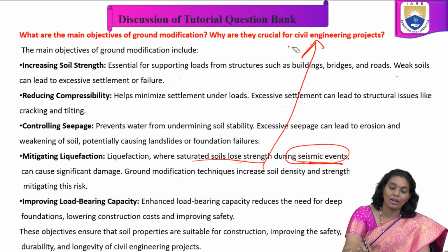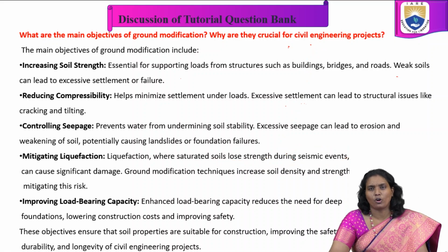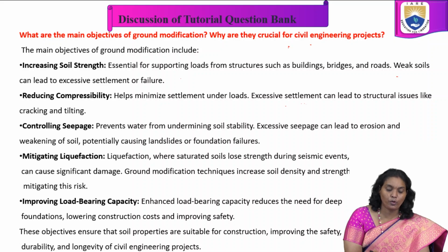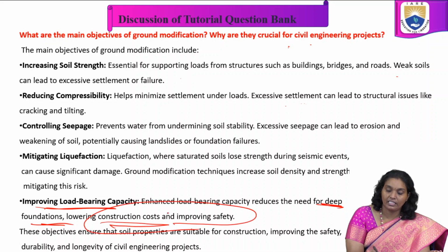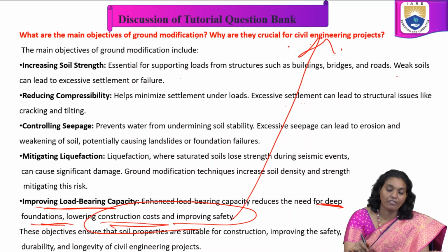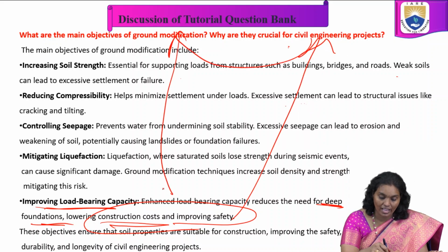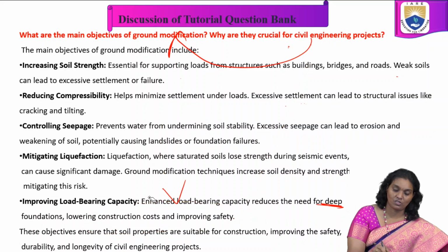Improving soil bearing capacity is one more objective of ground modification. It enhances the load bearing capacity, reduces the need for deep foundations, lowers construction cost, and improves safety. This is also a civil engineering concern. Using ground modification techniques, we enhance the load bearing capacity. We may elaborate on this one also.